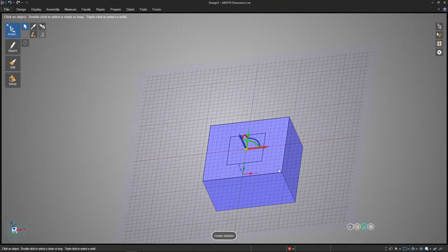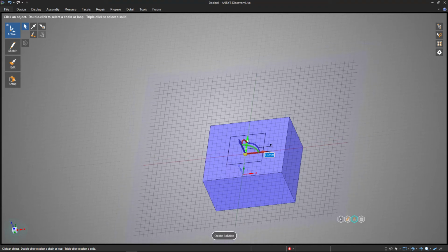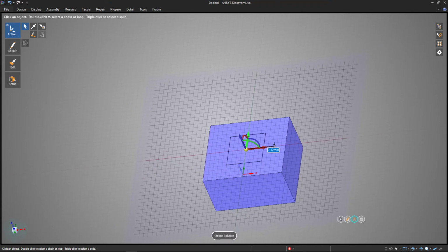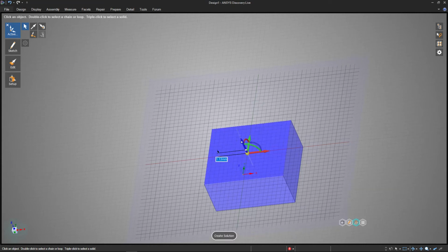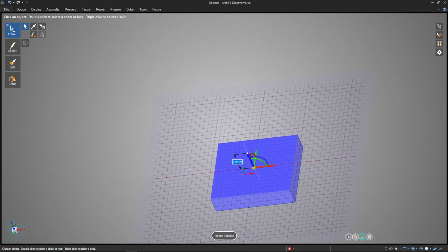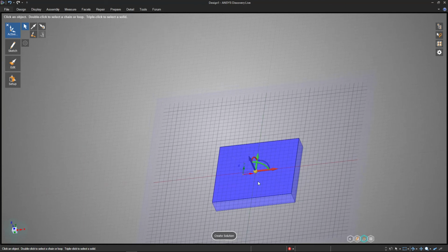So selecting this option, we get the move tool here, and it's always going to look like this when you're trying to move something. You can pick one particular axis and have it constrained just to that axis, and if you grab the bars in between, you can rotate. So I'm going to move this down to point out something that happens a lot. A lot of students think that their object or their 3D components here have been deleted by moving the plane. They've simply been hidden so that we can actually see the plane and not have them get in our way.